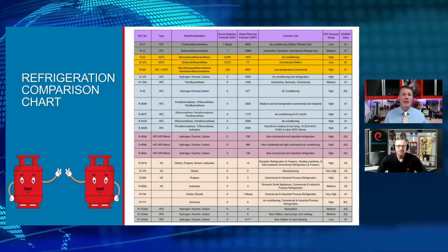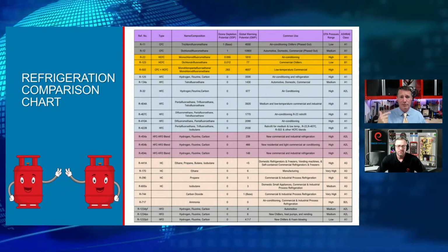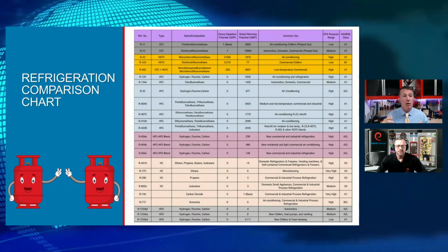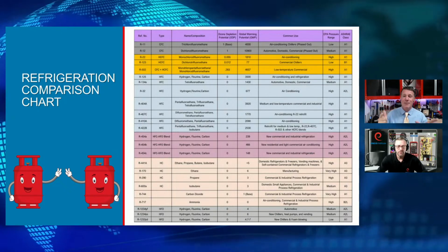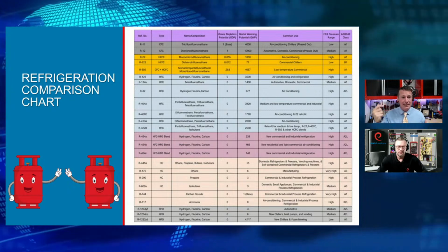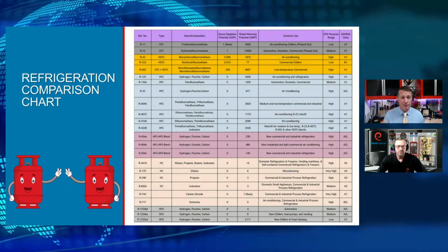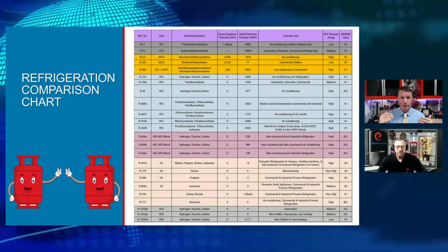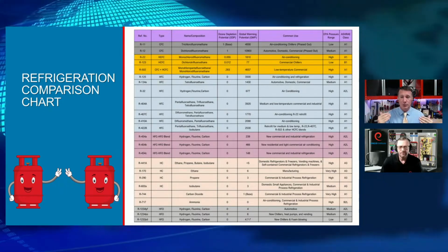So let's talk a little bit about our refrigerant transitions before we get too deep into what the new refrigerants are. Now, I have added quite a few of these. If any of you out there are ESCO EPA 608 proctors, you'll be familiar with this chart, except it's added in with some additional refrigerants. So I've added in our 454A, B, and C, and I've also added our 1234yf, ze, and zs so that we can see these refrigerants in comparison to our previous generations and why we're continuing this lineage.